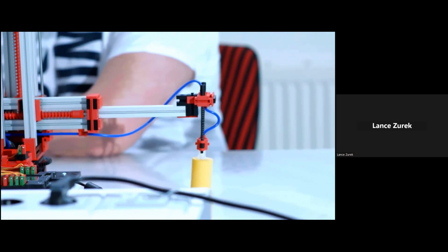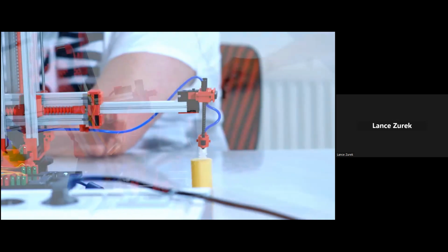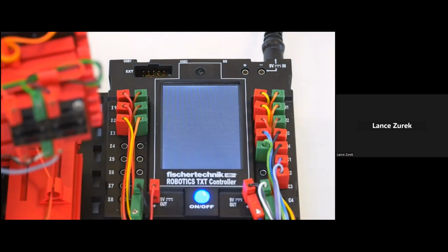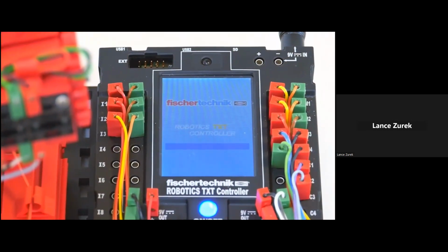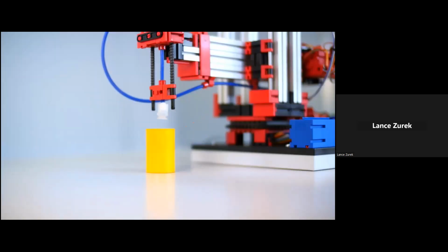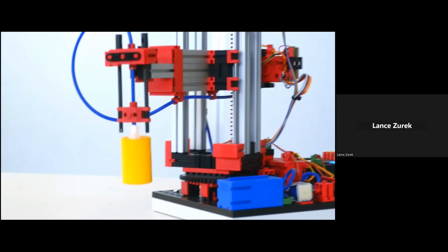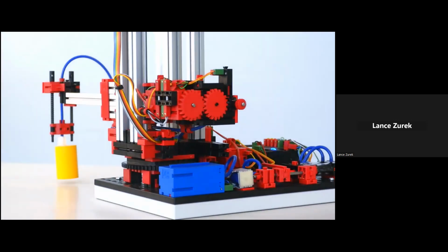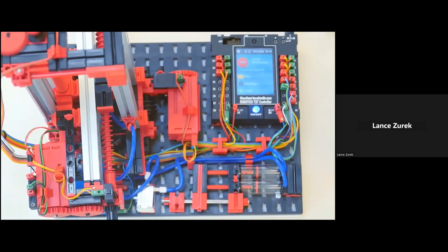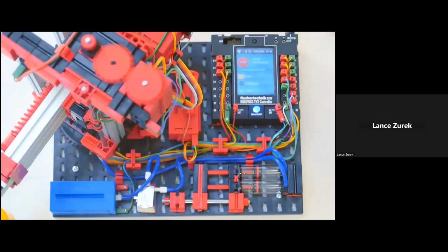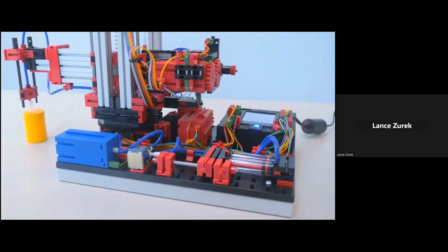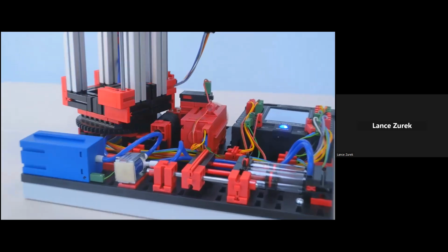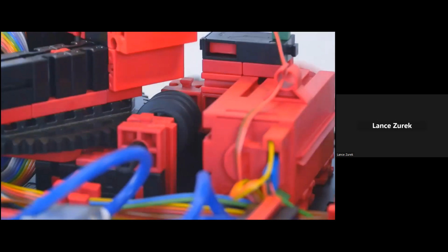The model's dimensions are approximately 9 by 19 by 15 inches, and it has a weight of just about 7 pounds. The 24-volt versions of this model, as well as the other 24-volt models we're going to be looking at coming up right here, each have a relay board for motor polarity reversal and both a multi-pin connector, 26 pins with a grid of 2.54 millimeters, as well as additional PCB terminals with push-in connections for all inputs and outputs. Again, the 24-volt version of this model, as with all of the 24-volt versions, will require you to provide the PLC and the programming.